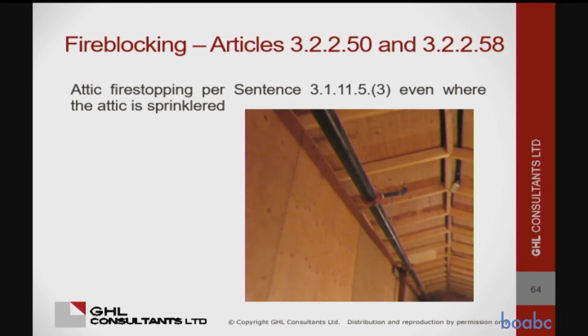So the items related to 6-story wood frame buildings, when it was only in the BC code, they were all in 3.2.2.50. And now in the national code, they're spread all over hell. And then you're like, oh my God, I never noticed that one before. So there's a handout up here if you want one after, that has every item related to 6-story wood frame buildings all in one table with the code references, and they're all there in one place, and you won't lose any.